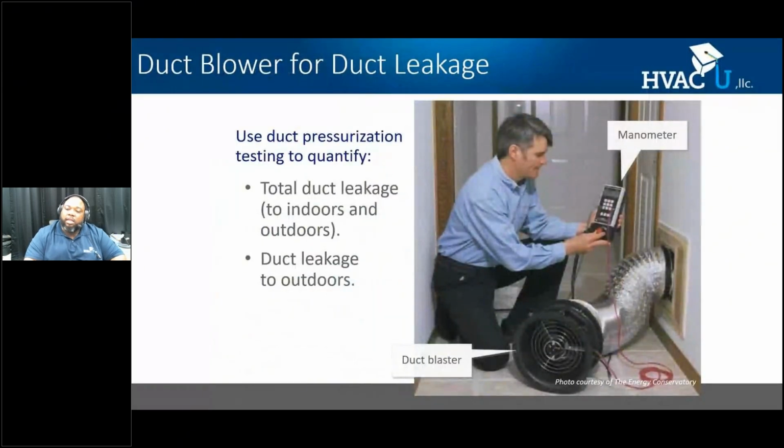The next thing we're going to talk about is a duct leakage test. A duct leakage test is this system right here, and it basically has a duct blower, or a baby blower door, as my son calls it, and it has a duct that connects to a duct system, and it's controlled by a speed controller or a manometer. When we use a duct leakage test, there are 2 tests that we can perform. We can get total duct leakage. If I have a certain CFM duct system, it measures how much is leaking in total, which is important. It tells me how leaky the ducts are.